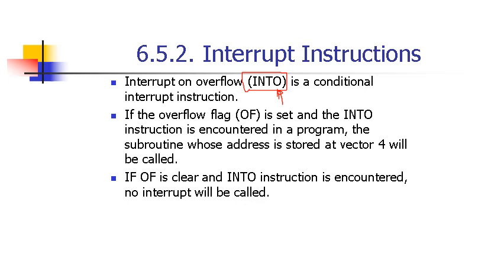So from time to time you should check your overflow flag bit to see whether it's raised or not, and when you place INTO inside your code, it will warn you and give you a message whenever an overflow takes place.